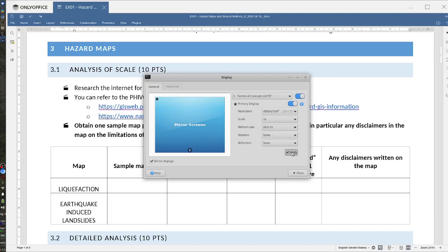And then the third part is to open the historical earthquakes. Find the three largest historical seismic events within 200 kilometers of your site. List down their date, magnitude, and coordinates.